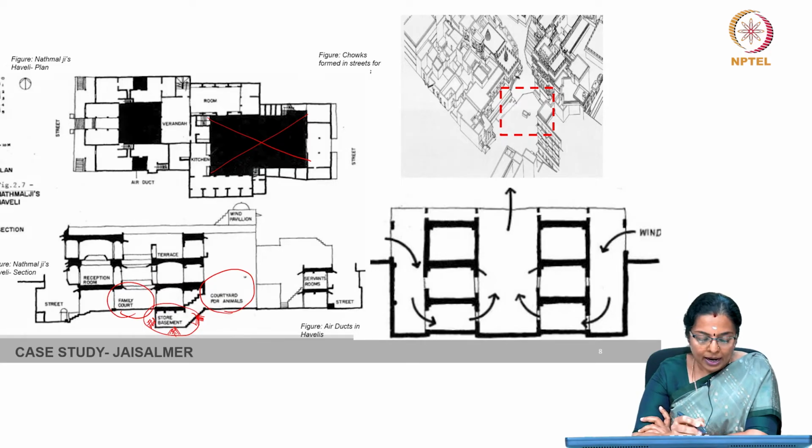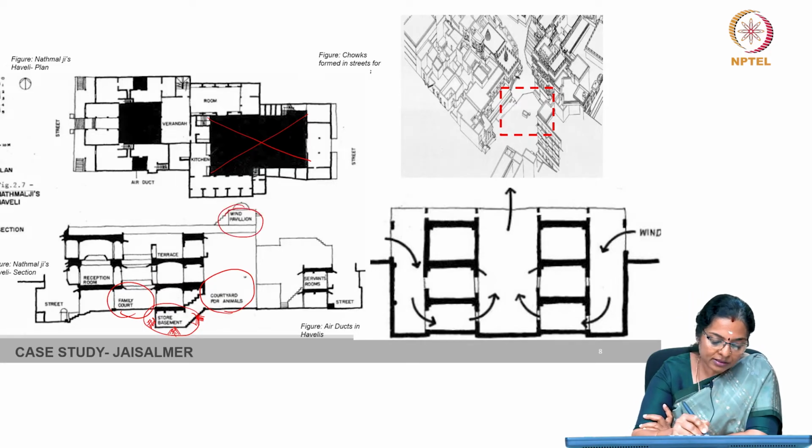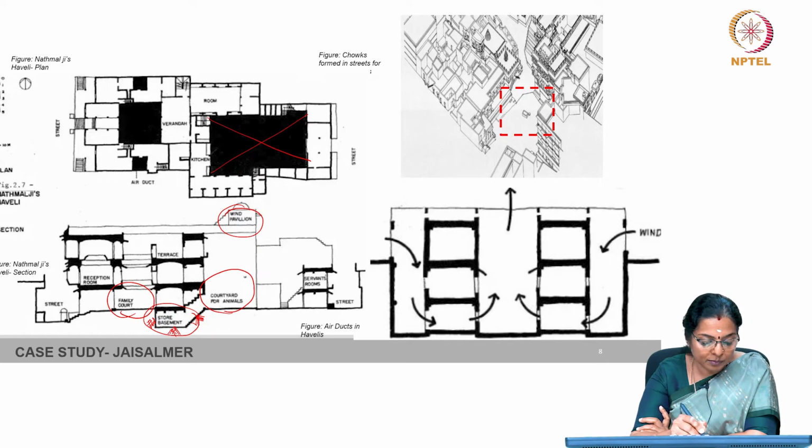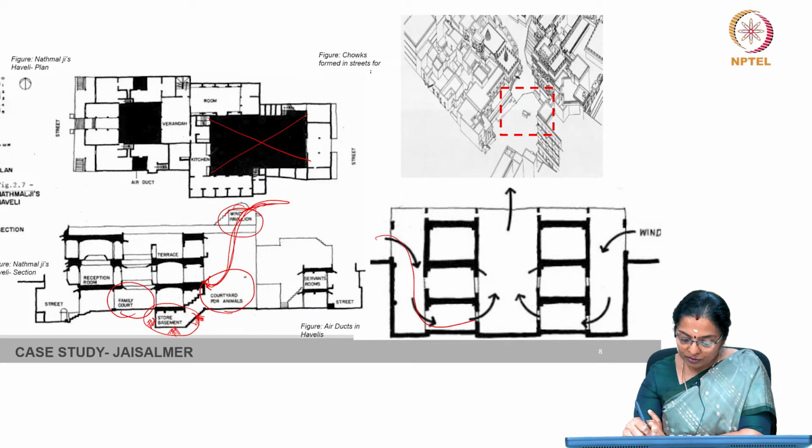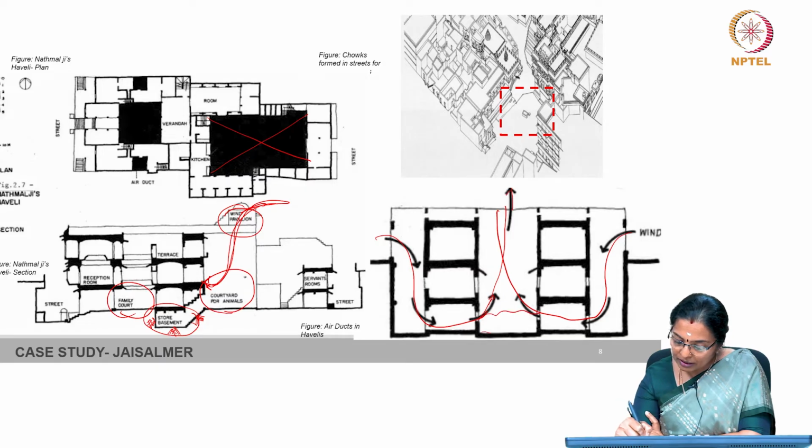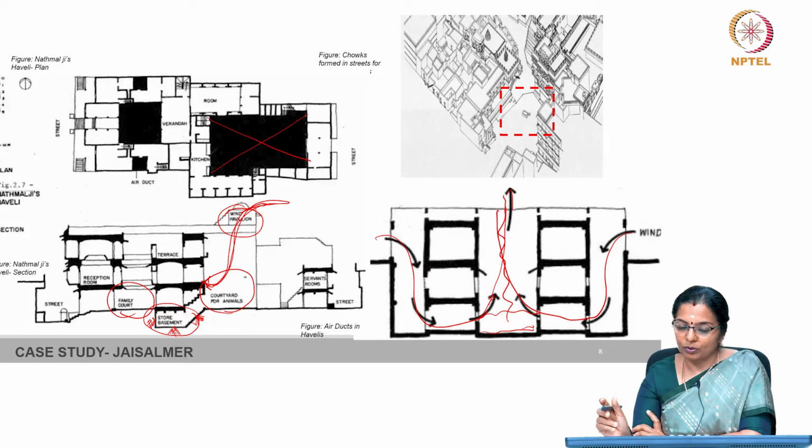And then you also have wind pavilions which help in diverting, because hot air rises up and cool air sinks below, and this air movement through the pavilion and the courtyard also helps in ventilation. So, the courtyard serves as a vent for the air or the wind to go, and therefore any hot air which gets generated here rises up and moves out.